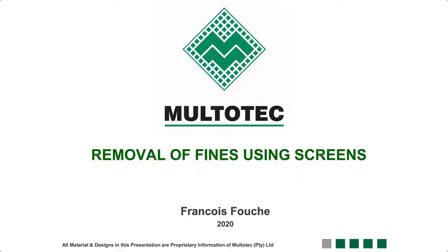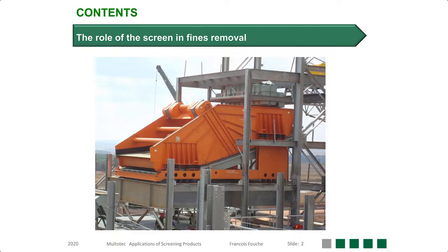The topic of this morning's discussion is the removal of fines using screens. Irrespective of the mineral that you recover, the removal of fines is an important step in your process. The fines fraction can be removed by utilizing vibrating or static screens. The optimum solution will depend on the correct combination of screen and screen media.